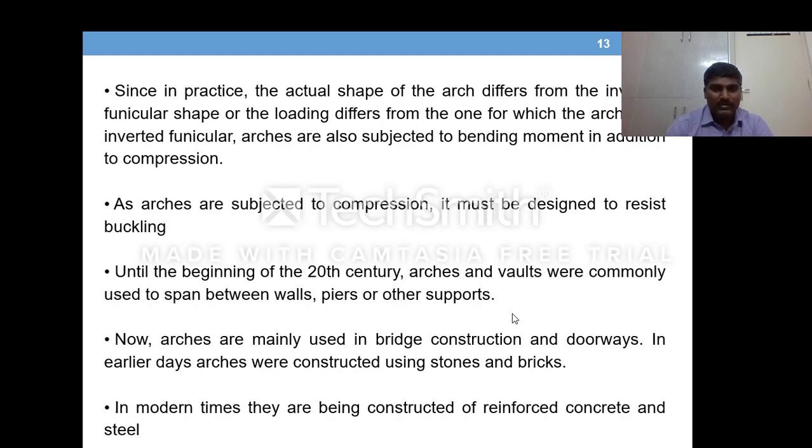As arches are subjected to compression, they must be designed to resist buckling also. It's a very common phenomenon. You might have studied it in dealing with columns, where slender columns come across this concept of buckling.